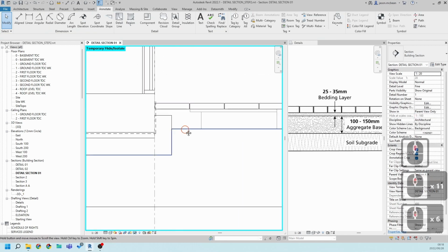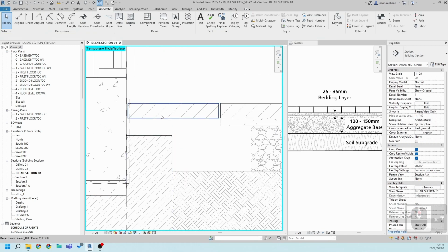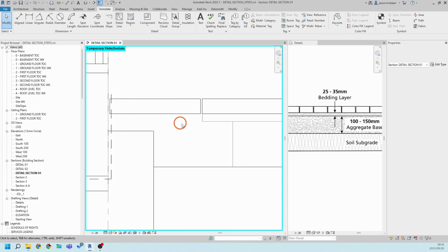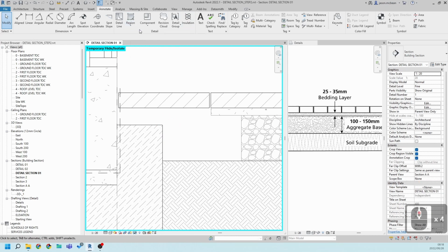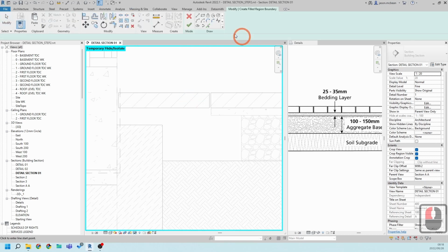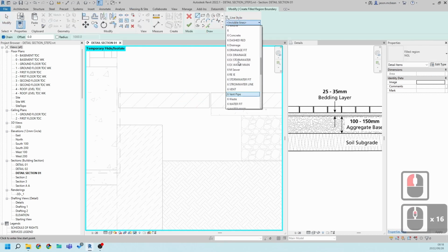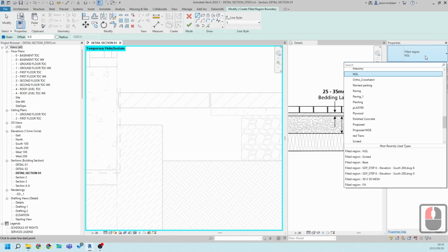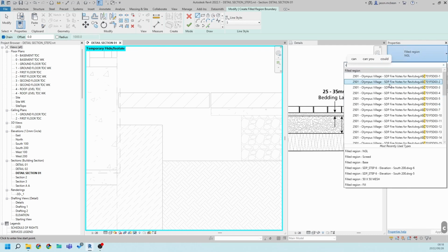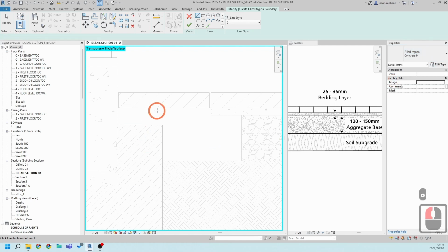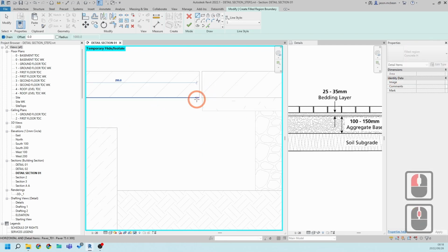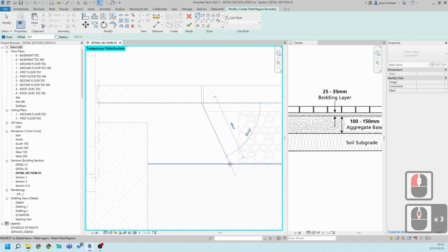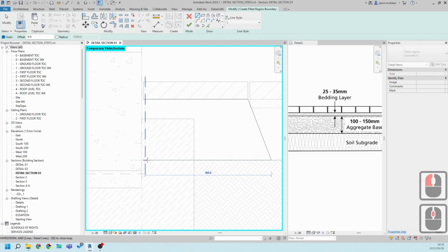Okay, so here I need to make some adjustments. However, I am going to have a haunching line here, so I need to show some concrete haunching. So let's do that quickly. So here I'm going to go to region. Here you can get away because technically it's not structural, so you can use a 5 line weight line, and you're going to change this to concrete because technically this is a weak concrete mix. So concrete. Grab this line for the time being, and then this will typically come down at an angle. That's totally up to you.